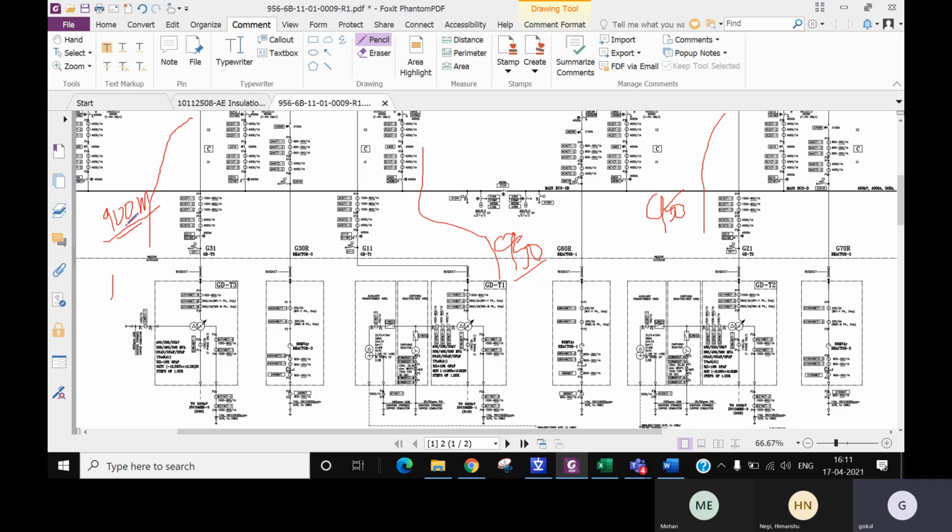Yes. So then you have to get that AutoCAD file, and you have to comment on which transformer has the longest path and which transformer has the shortest path. If you take the longest path, then there will be two cases: energization and de-energization. Would you do this ferroresonance just for the high voltage or any voltage? Any voltage we can do it.